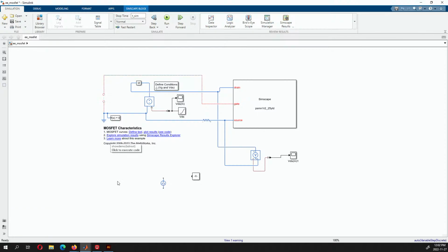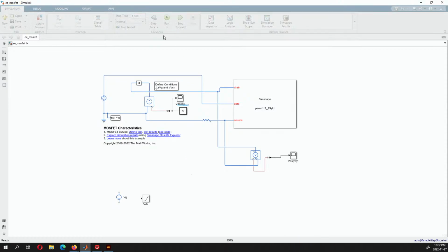So all I'm going to do is just exchange this from a ramp to a pulse. So that matches the data sheet. That's a good way to simulate to see whether you got the right model and it's matching what the data sheet tells you. Now you would also want to conduct the actual experiment, because with the data sheet, all they've done is basically simulate the SPICE model, and that's not a good idea.